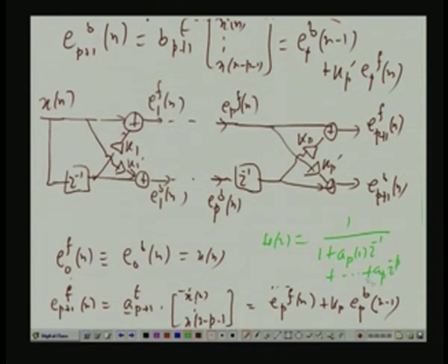Now, this is the all pole transfer function. For this model to be viable, that is stable and causal, the poles must lie within the unit circle, and we will show that by solving the Yule-Walker equations. Whatever coefficients you get, those coefficients indeed ensure that the roots here, that is the poles, that is the coefficients AP1, AP2, up to APP, are such that the corresponding poles are indeed within the unit circle.